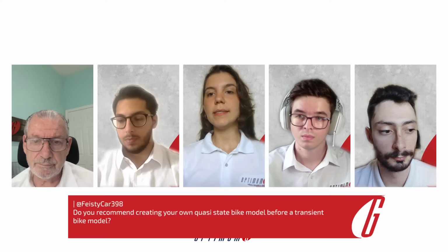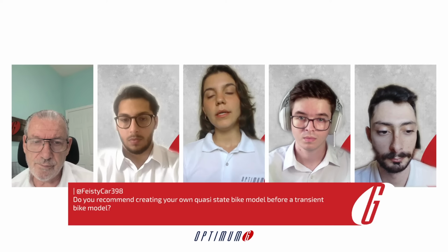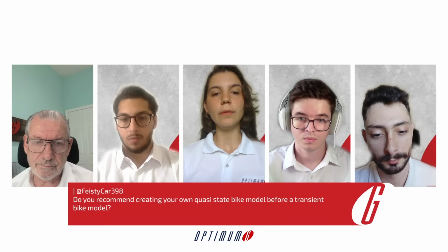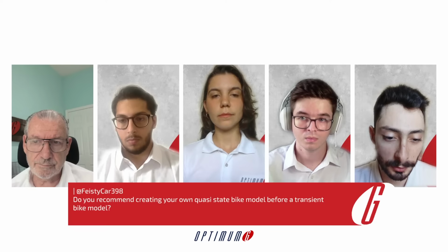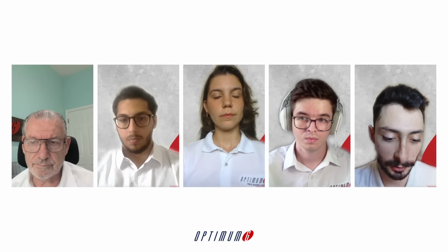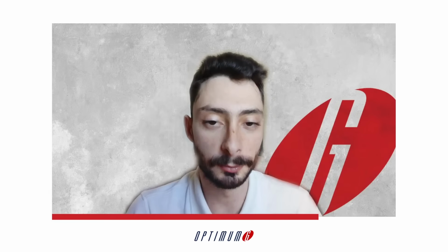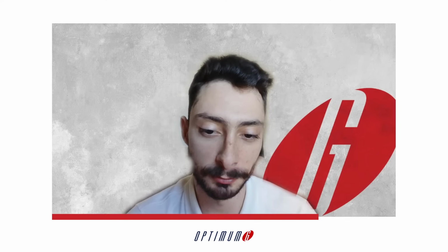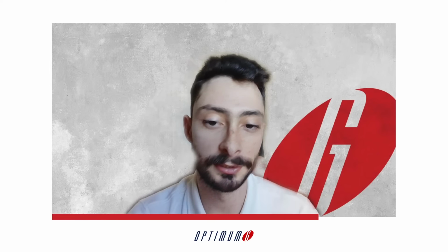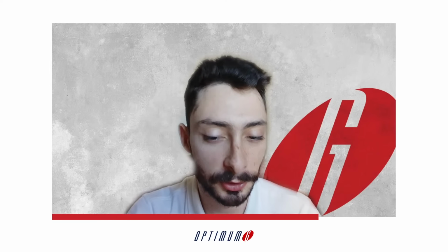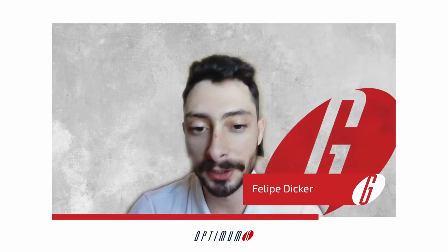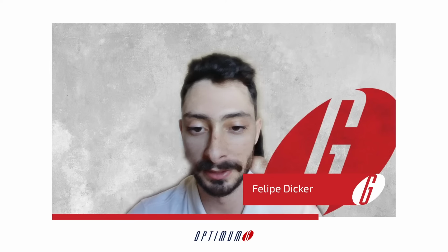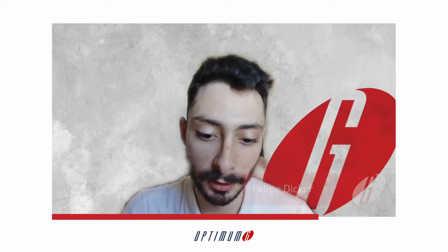The next question is coming from Car. Do you recommend creating your own quasi-steady bike model before creating a transient bike model? Yes, absolutely. For two reasons. First, because we need to start with the simple stuff, and it's a lot easier to do a steady state system than a transient system, simply because in steady state you don't need to necessarily work with differential equations. You don't have a time step involved. You don't have the previous state of the car influencing the next state of the car, because everything is constant.